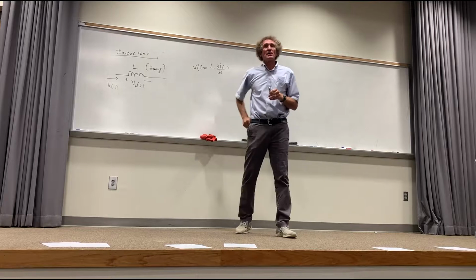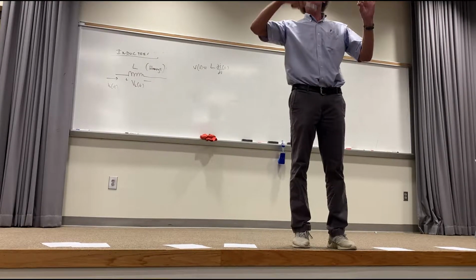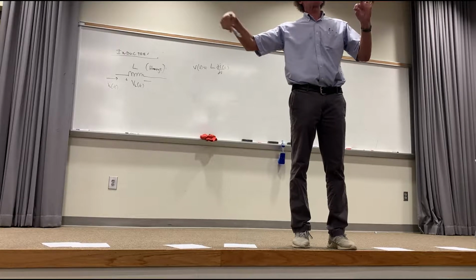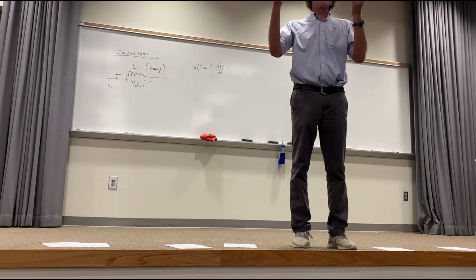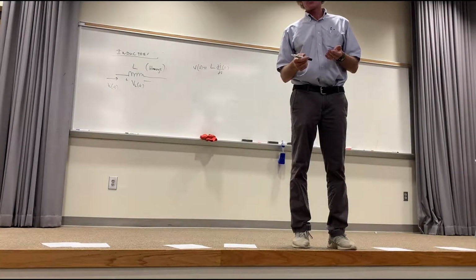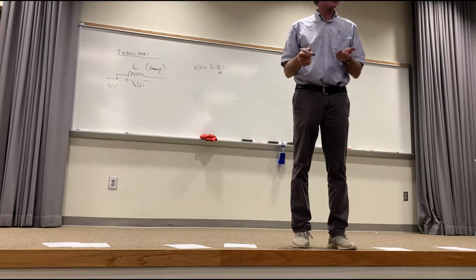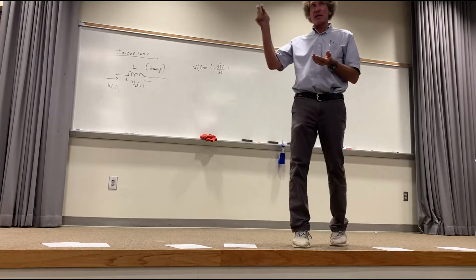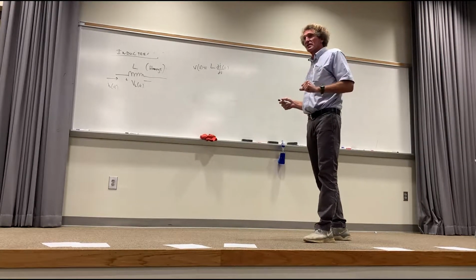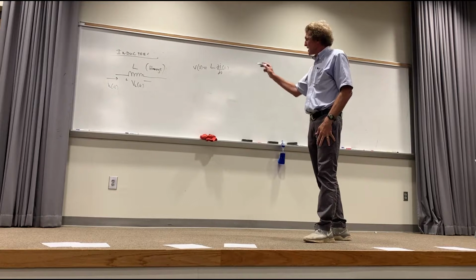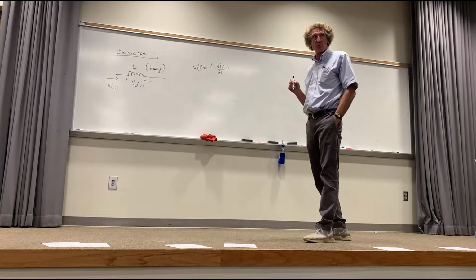What is an inductor? Probably the best way to think about it, from physics, you remember this? It's just a coil of wire. The thing that makes an inductor work is the storing and then recovery of magnetic energy. It's stored in an inductor. A capacitor stores electrostatic energy in a field. An inductor causes a magnetic field that stores the energy. So an inductor, in some senses, is an energy storage device. That is the relationship between voltage and current in an inductor. Now this is important that you see this.